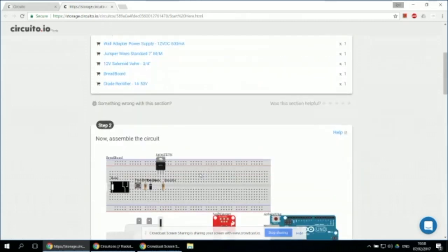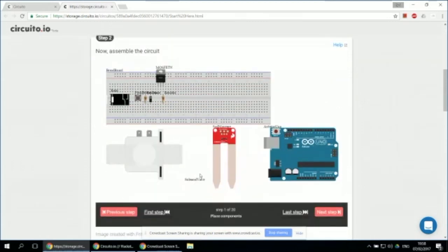So this is our promise to you that we are doing our best to make everything work for you out of the box. And we are building the circuit showing all the auxiliary components. So you can see, for example, the push button. It's best to use it with a resistor. So we have the resistor. We have the diode for pushback from the solenoid valve and the MOSFET to drive the solenoid valve. Really things you don't need to know about that we know about, and we take care of it for you. And you can just go and build a circuit using the step-by-step and see all the wiring and stuff.